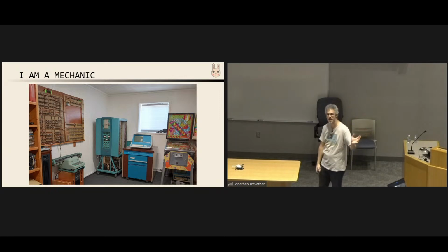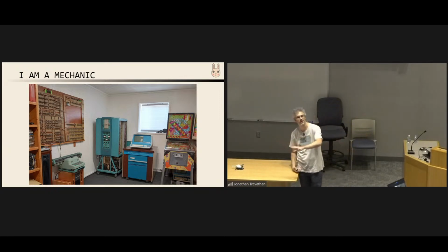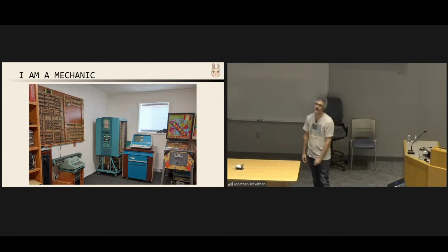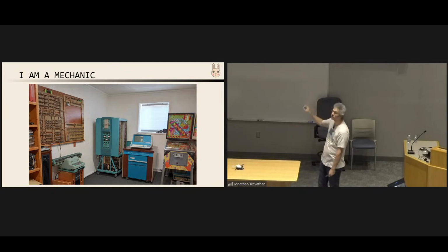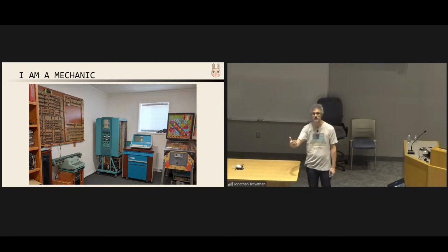It's got about 460 vacuum tubes in it, somewhere around 3,200 germanium diodes. And currently, it doesn't work, but we're very, very close. It has a rotating drum memory in it that has about 7 kilobytes of storage on it. And we think that the drum itself is made out of titanium, which is pretty fancy materials for 1956. We've actually managed to boot the machine, but it's not executing code quite yet. It knows where it needs to go to start executing code. You hit go and it doesn't go there. So we've got a little more troubleshooting to do on it.